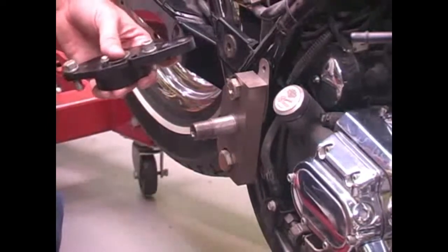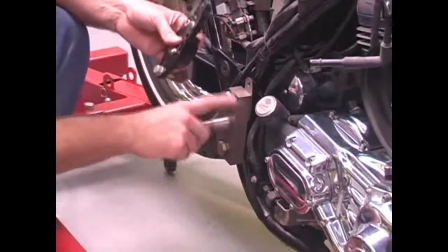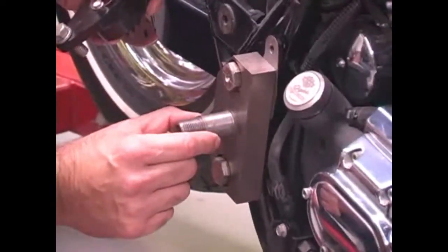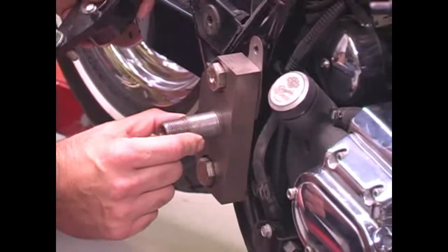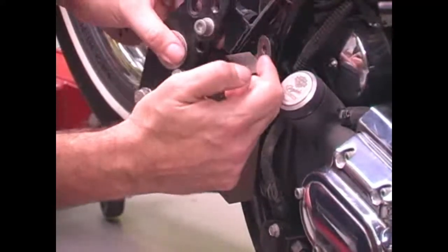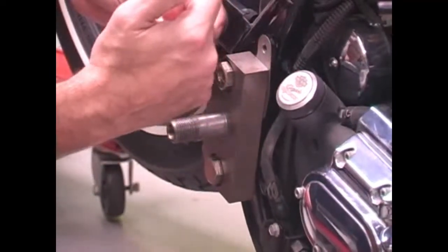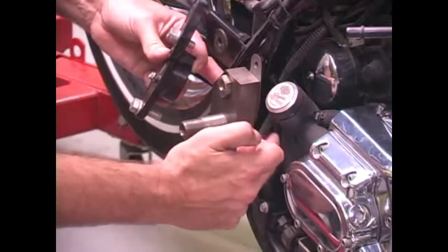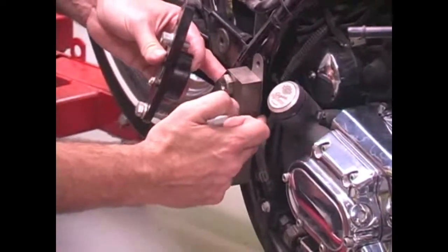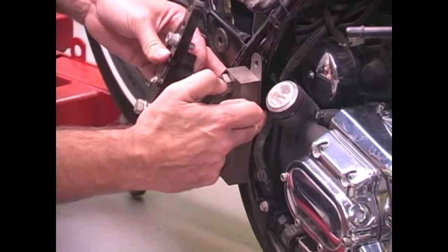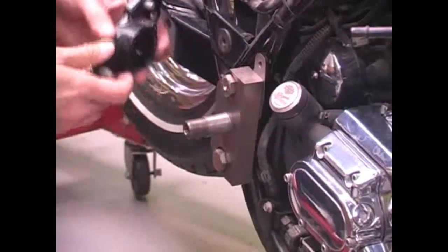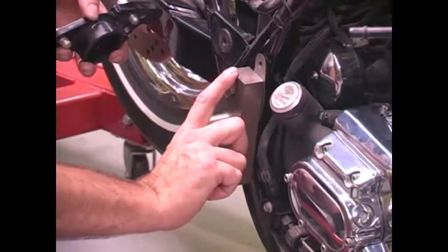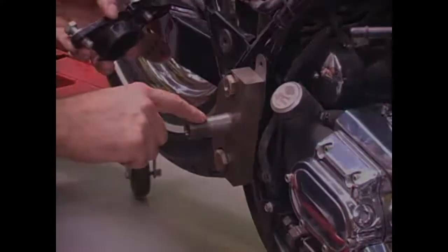So what I've done for this tooling is I've built a spud on here, so this is able to accept the tooling holder on the jig. And then I've milled, if you see the top of this, one of these things that's been milled in half. The reason I've done that is so that it holds the elastomer, rubber, however you want to say that thing, the piece that locates the engine and transmission, which is still being held in place from this piece of tooling. I have my adapter to the jig put on top of there.